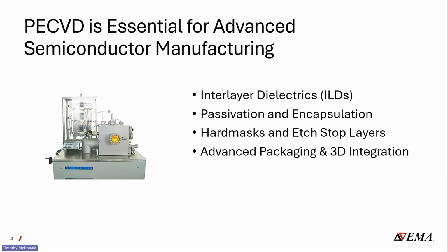PECVD is essential for advanced semiconductor manufacturing. Think smaller than 16 nanometers. First, interlayer dielectrics. These are used for insulating films between metal layers and back end of the line. Low-K dielectrics are commonly deposited using PECVD technologies.